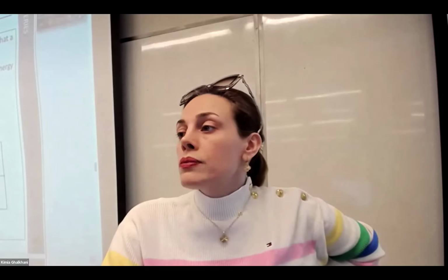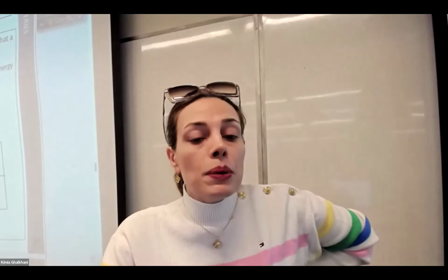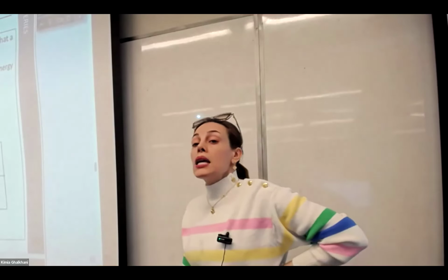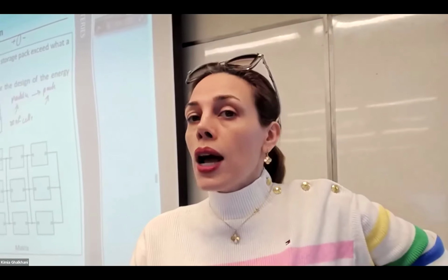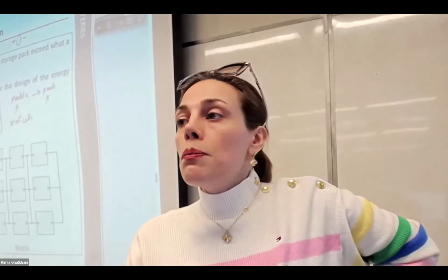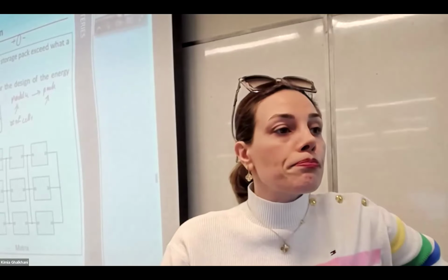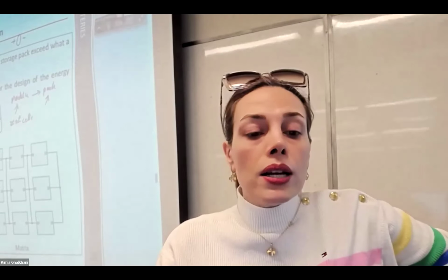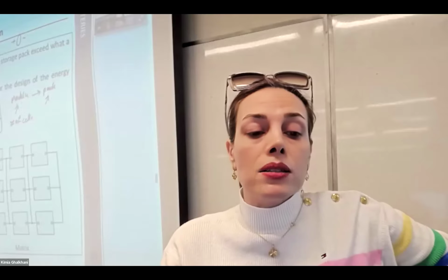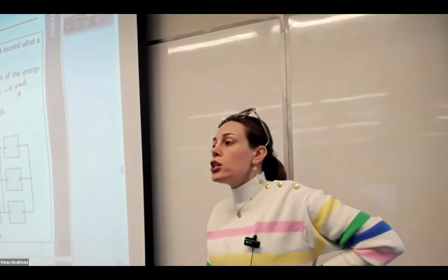How about current? If I'm having such a scenario, it simply means I'm going to increase the total voltage compared to my initial voltage for each of these modules. It's not even close, right? Therefore, my total voltage for this kind of connection is a combination of all of these voltages. How about current? Current in here is equal. Current, if I say IT, means total current, or you can even say capacity. Current and capacity for each module or each cell are talking about the same thing, meaning how much power they are going to generate.